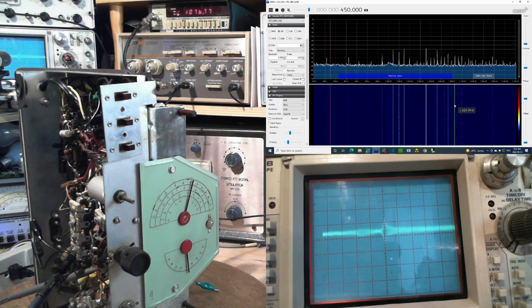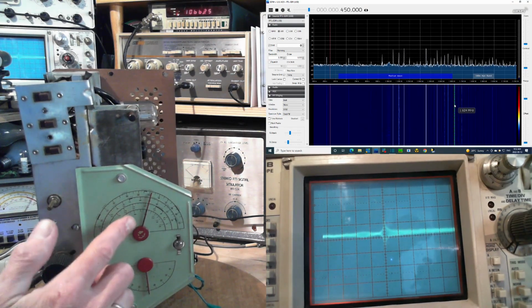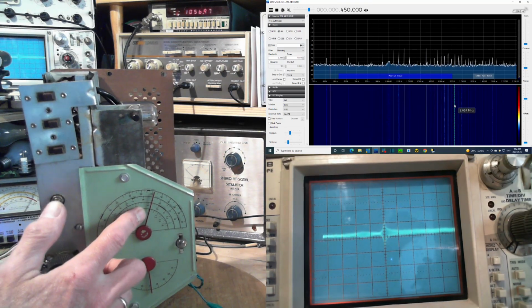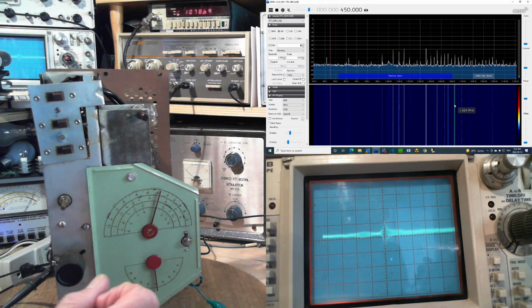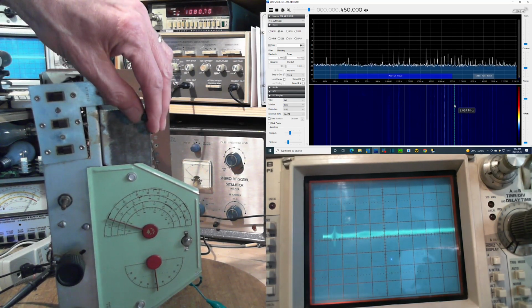Is the radio really tuned to 1,000,000? That's what I wanted to look at. So we're looking at the tuning. You know, it's bang on. It's right dead on 1,000,000. So that puts the front end tuning right in line with the pointer here. Let's try another spot. I don't even have the radio operating and I'm able to do this.